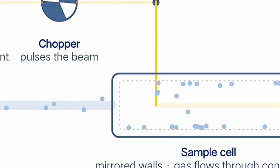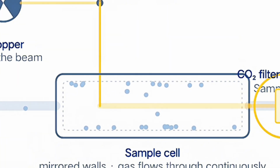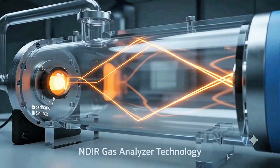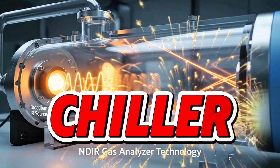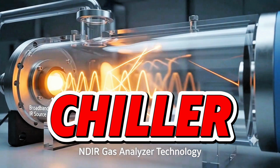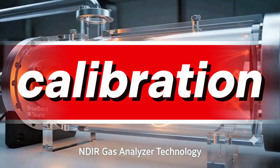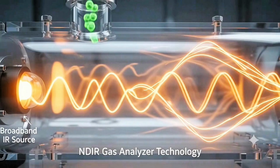What this means for fault finding. So when you get a suspect reading, think about it in this order. First, is the sample even reaching the cell? Check pump, filters, and sample line for blockage or leaks. Second, is the sample dry and clean? Check the chiller and condensate drain. Third, is the optical path clean? A fouled or scratched cell window will attenuate the beam and read low. Fourth, when was the last valid zero and span calibration? Drift here is often the real cause of a reading that looks off, but isn't a hard fault.